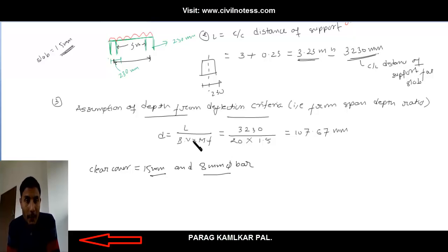After using these, I want to determine the depth. The formula is d plus clear cover plus diameter by 2.